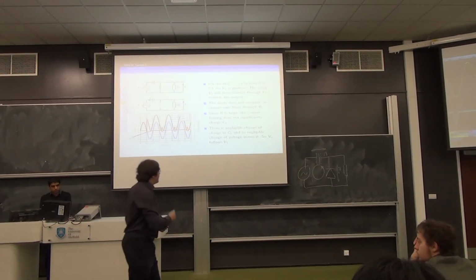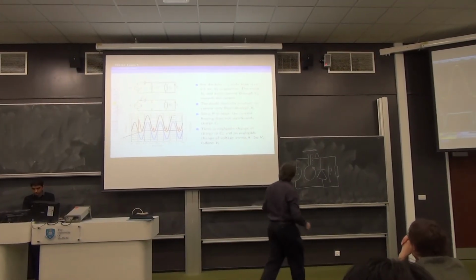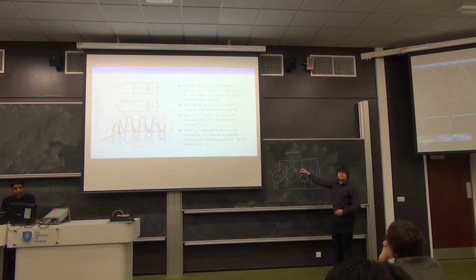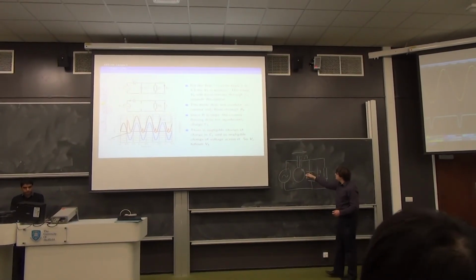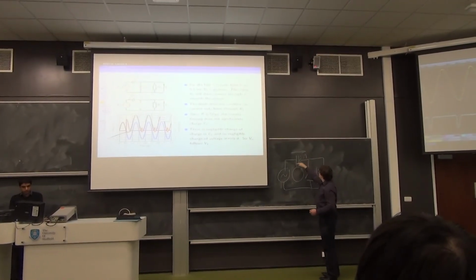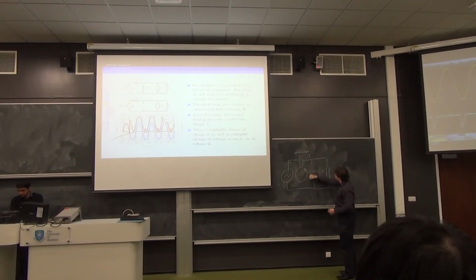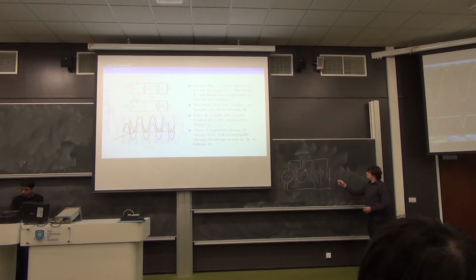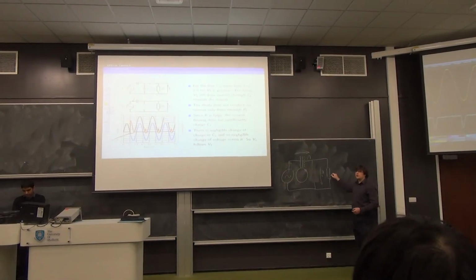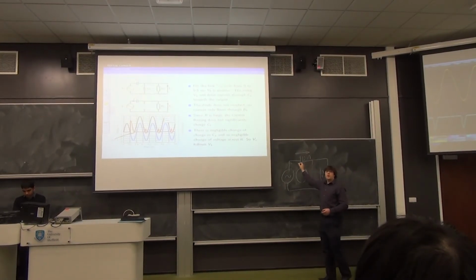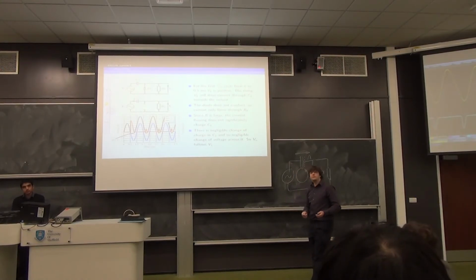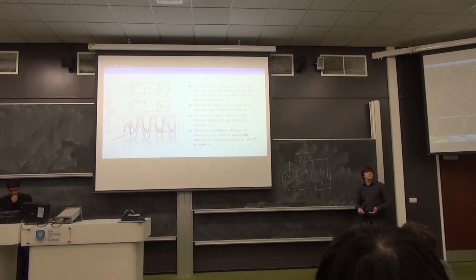But for now anyway, the capacitor's charged up, and this input voltage waveform starts to rise again. And as it's rising, we must have some change in voltage here as well, because the diode is not conducting, so I can say, well, it's not there. And I have to go back to my original situation where the resistor is quite large and it can't change the voltage on the capacitor very much because we can't take enough charge out to make much difference. So there's no change in charge, there's no change in V.